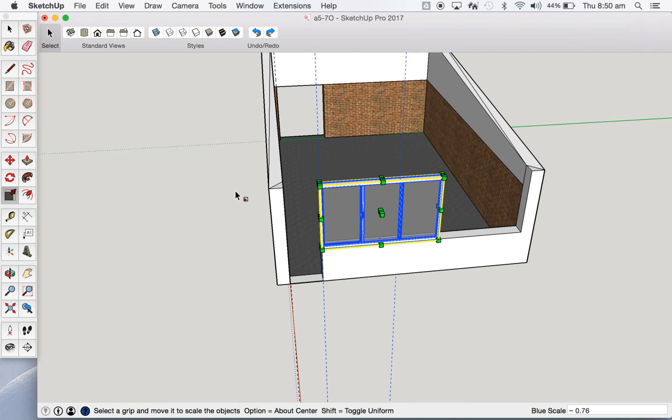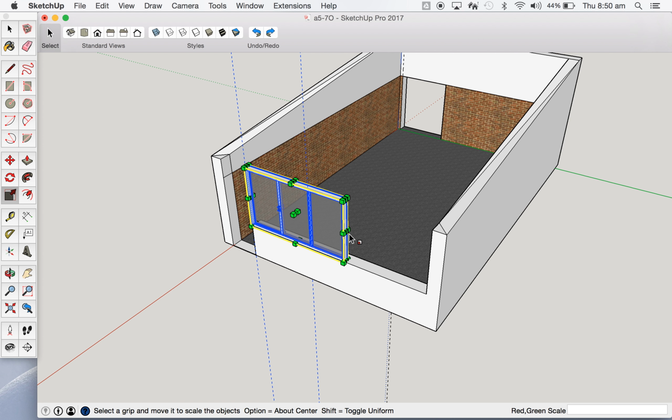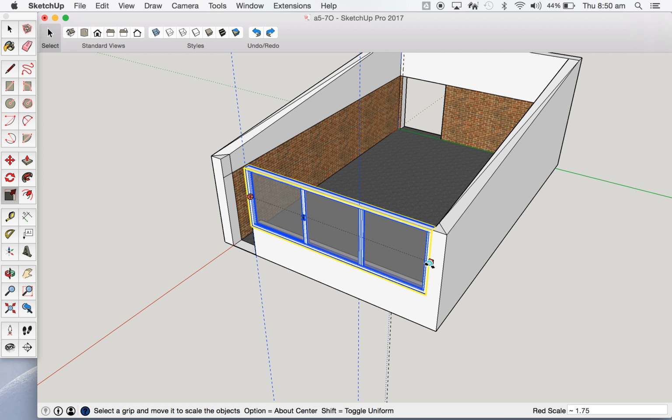Now we also have a problem in that it's a different width, but that's fine, because we've got two options here. We can copy and paste it, so we have two of them to fill up that space, or we can extend it. So I'm going to show you both. We'll go back to the Resize tool, grab that little handle there, click it onto there, and there we go. We've expanded it out to fit that space.